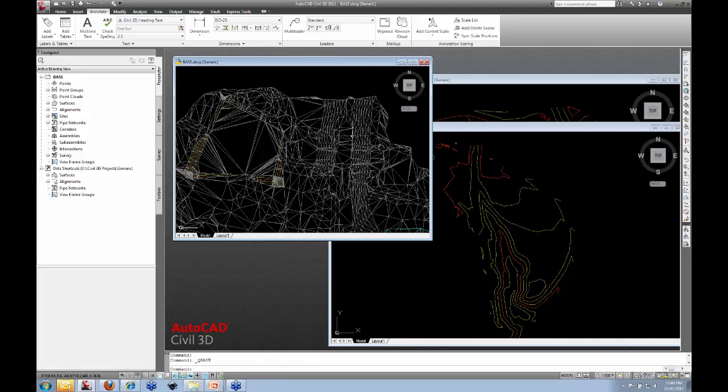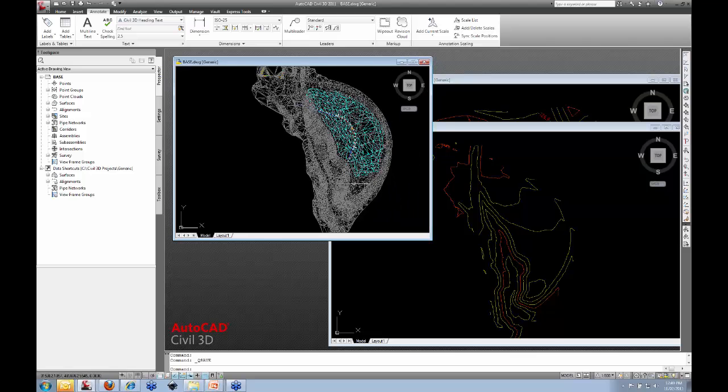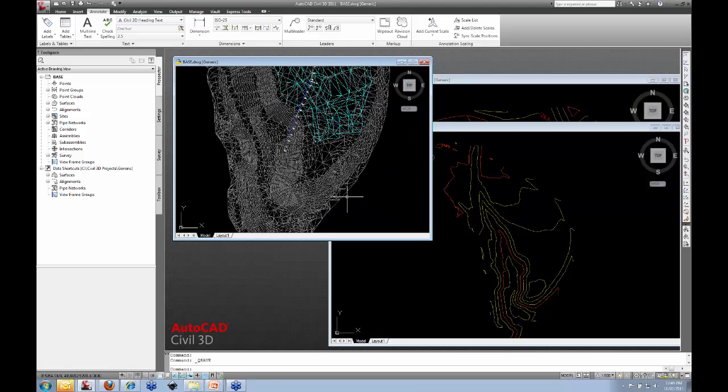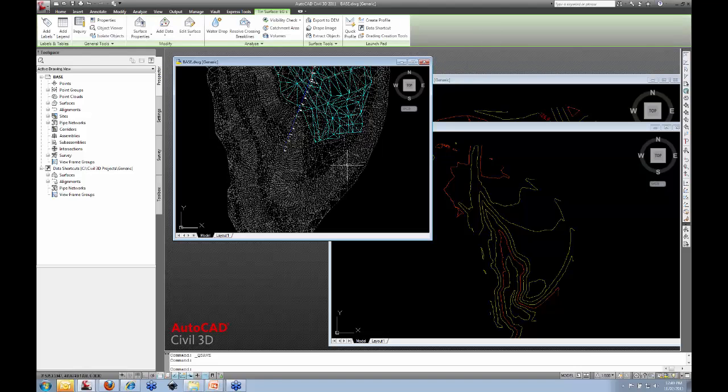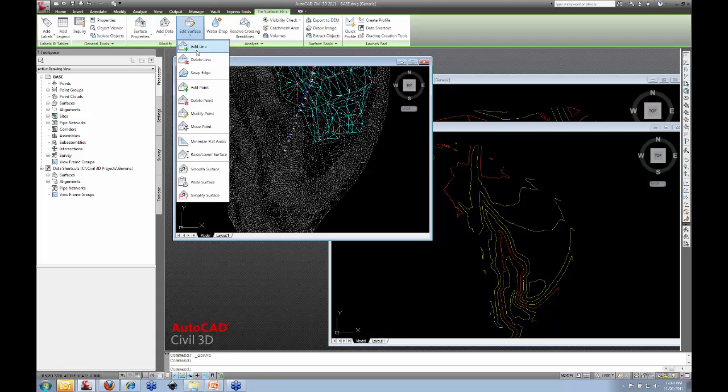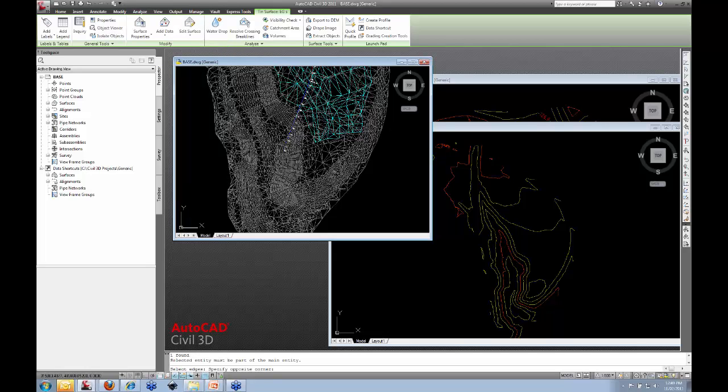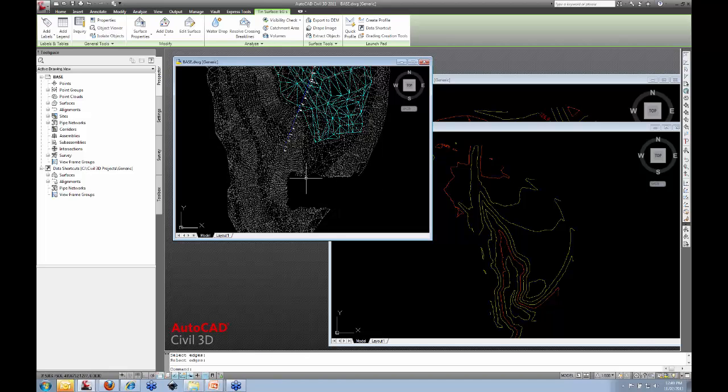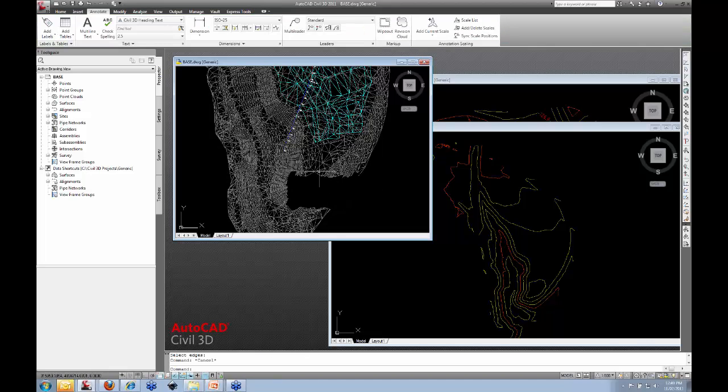And just to show the process working again, let's go back out to here. I'll do some butcher work and remove a chunk of geometry from the surface. So if I pick my gray triangulation on my base drawing, I'm going to select Edit Surface, and you will see an option here called Delete Line. Now again, it doesn't matter how you do this. I'm just picking the quickest method of doing it. So you can see I've created a big hole in my surface here. So again, I press Save,